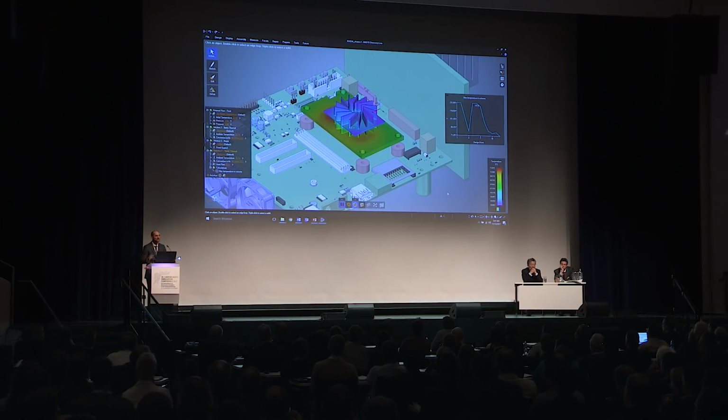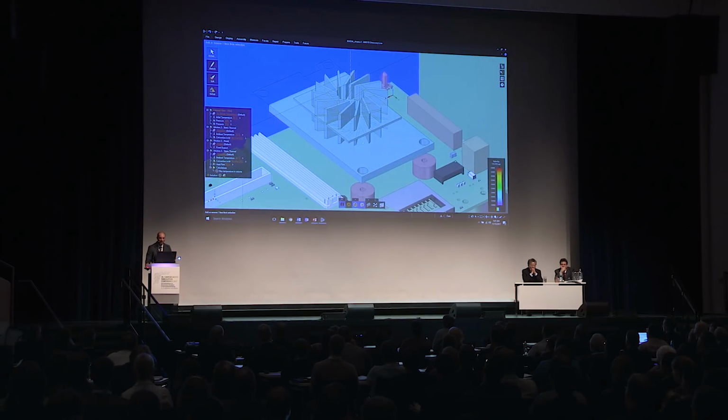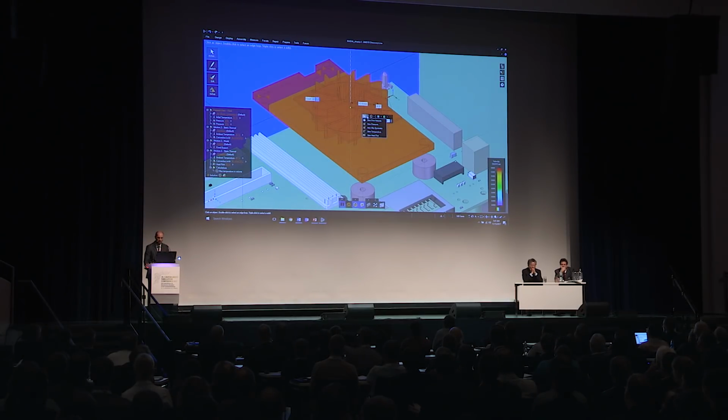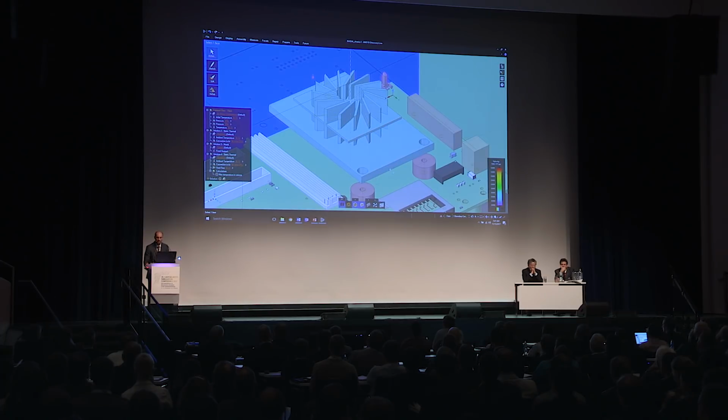But why don't we take it inside of this entire closure with all these detailed parts and look at its fluid behavior, right? So we did modal, structural, thermal. Let's do fluid in the same context too. To do that, again, this is pretty simple. All we do is flip over to a fluid simulation. In this case, I will assign a boundary condition. So we'll pick the faces on this heatsink and assign a temperature. Let's say we use the temperature that we just got from the previous thermal simulation. And now we'll also add gravity effects.